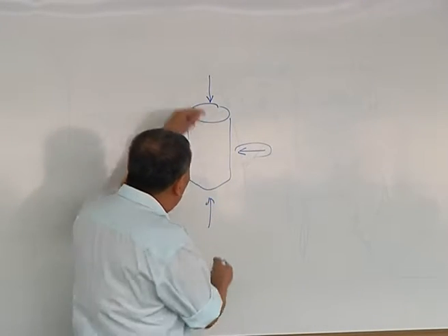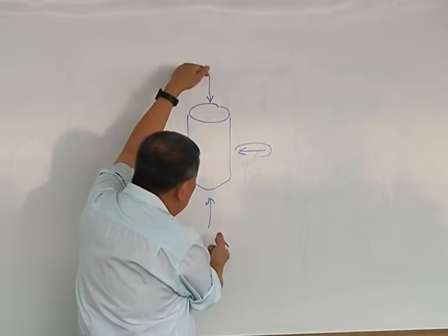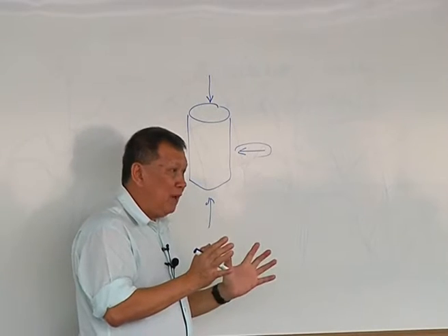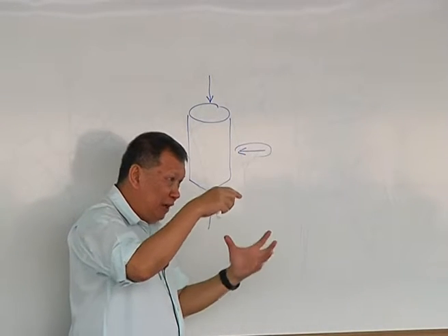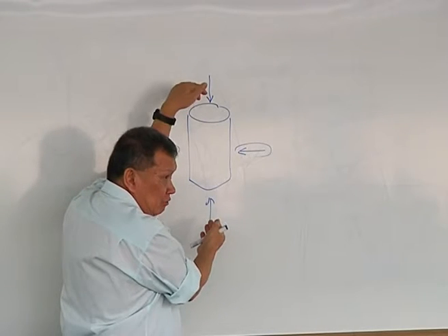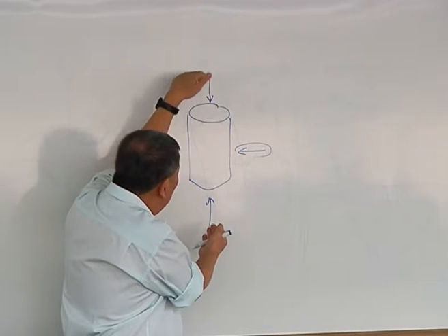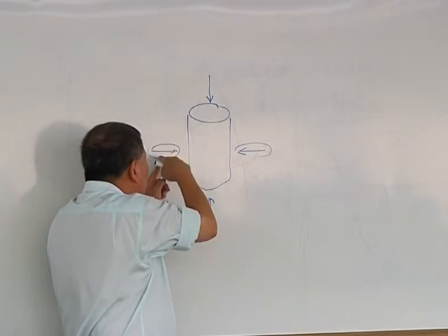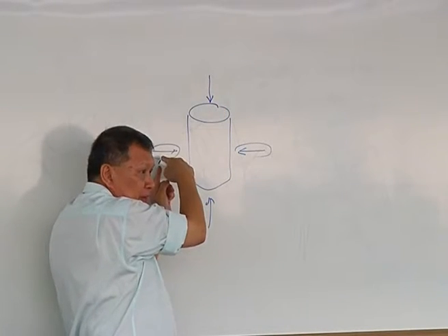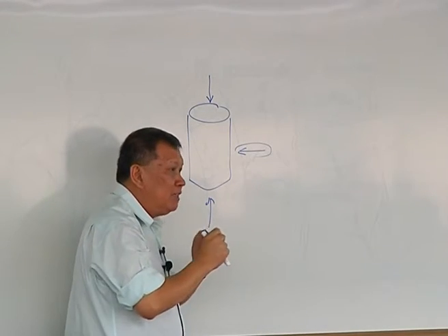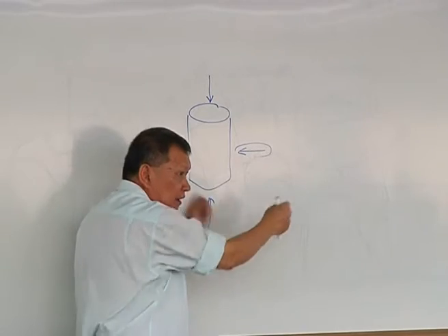So basically, okay, you reload it back, right? As you start to reload it back, at the start you will get no plastic strain because it's coming back to isotropic, but you will get some elastic strain. So you will keep loading it until this stress becomes bigger than this stress. And you can continue to keep loading it. Up to a certain point, the plastic strain will kick in the opposite direction.